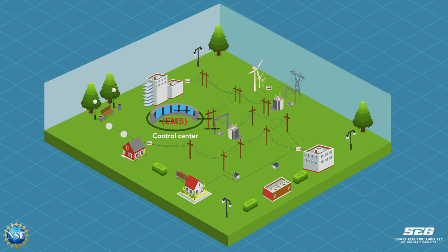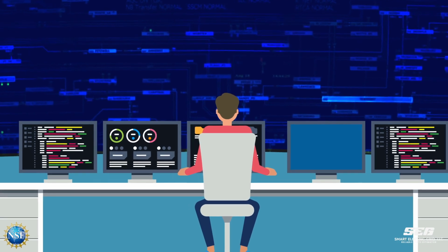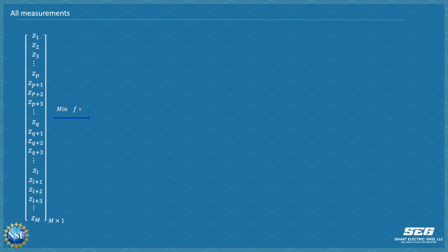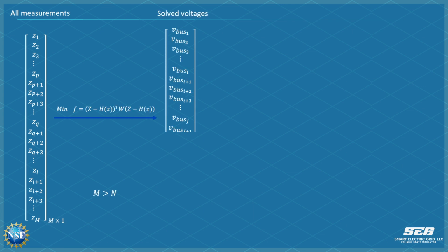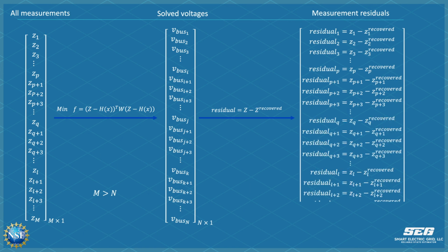With the assumed model and parameters, each real-time measurement can be written into a nonlinear mathematical equation called a measurement equation. To solve this set of equations, the weighted least square algorithm handles all the equations together and tries to find the optimal estimate of the bus voltages. This scheme is good when there are only noise or very small errors in the measurements and system model. However, this scheme will reach a biased solution as a sacrifice if bad data are present in the measurements and system model, because the residuals of bad measurements have to be minimized.